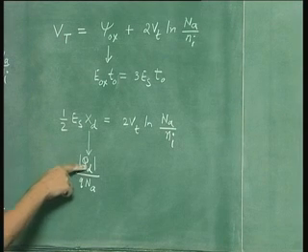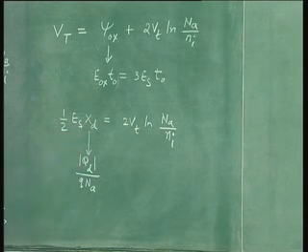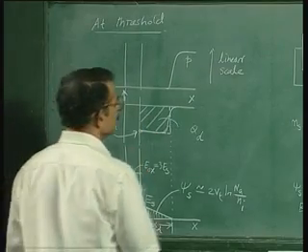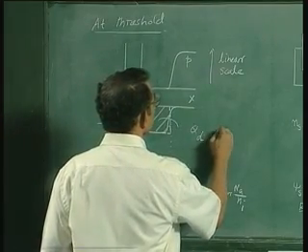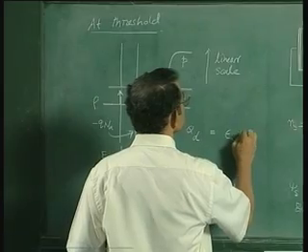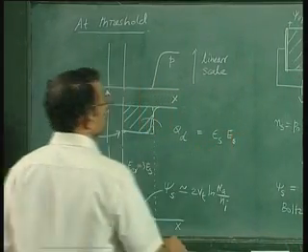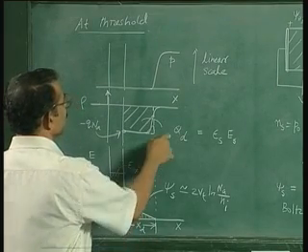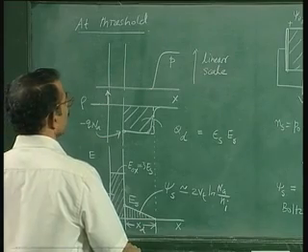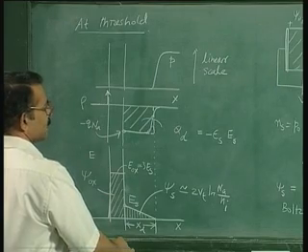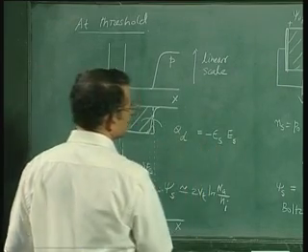And this QD and ES are related by Gauss's law, that is this ES and this QD. So what is the relation? The relation is QD is equal to epsilon S into ES, but ES is positive and the charge is negative. So QD is minus epsilon S ES, but modulus of QD is epsilon S ES.